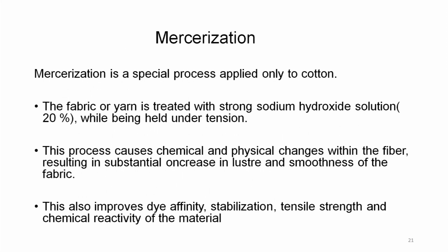Now, let us again look back at the textile processing. Mercerization is a special process which is applied only to cotton. The fabric or yarn is treated with strong sodium hydroxide solution as high as 20% while being held under tension.